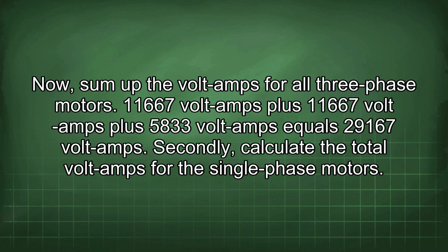Now, sum up the volt-amps for all three-phase motors. 11,667 volt-amps plus 11,667 volt-amps plus 5,833 volt-amps equals 29,167 volt-amps. Secondly, calculate the total volt-amps for the single-phase motors.